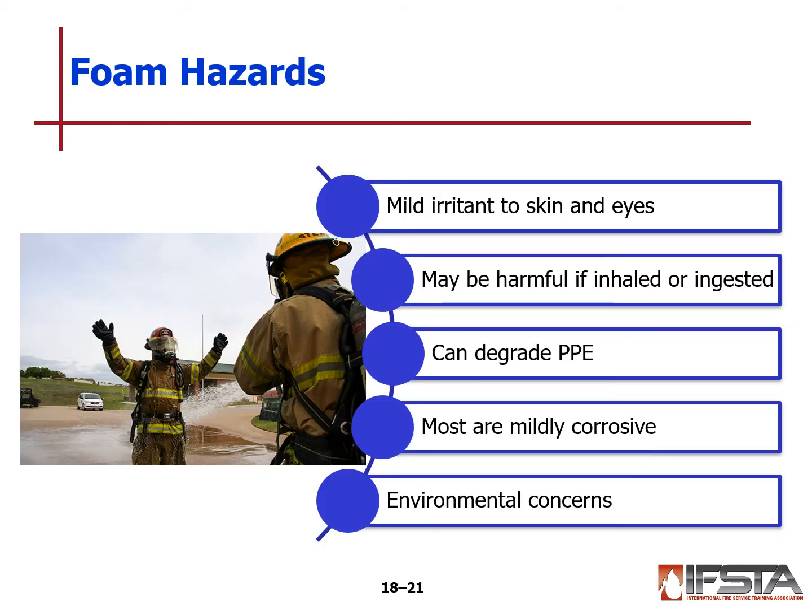Hazards of foams: these concentrates can be mild irritants to the skin and the eyes, may be harmful if inhaled or ingested, can possibly degrade PPE, and most are mildly corrosive. And with that, we can have some environmental concerns.